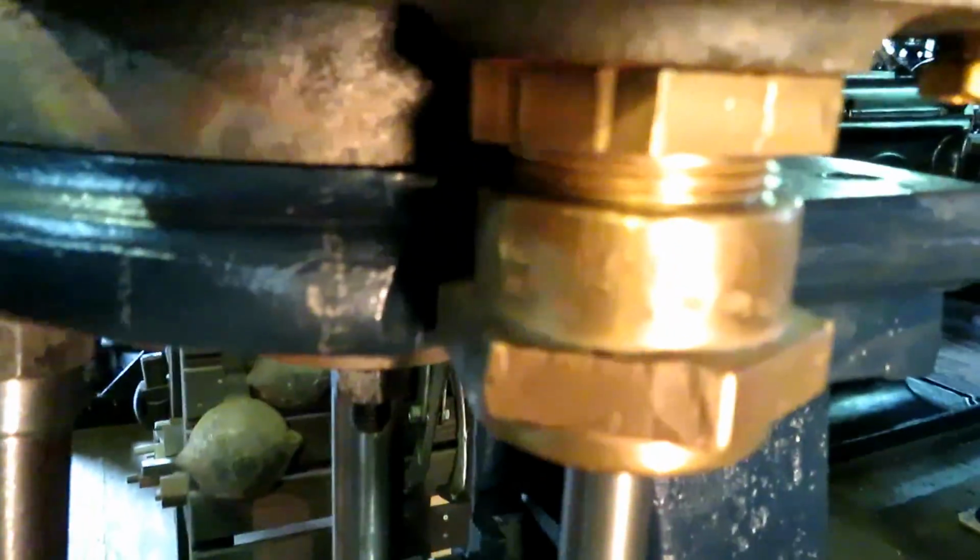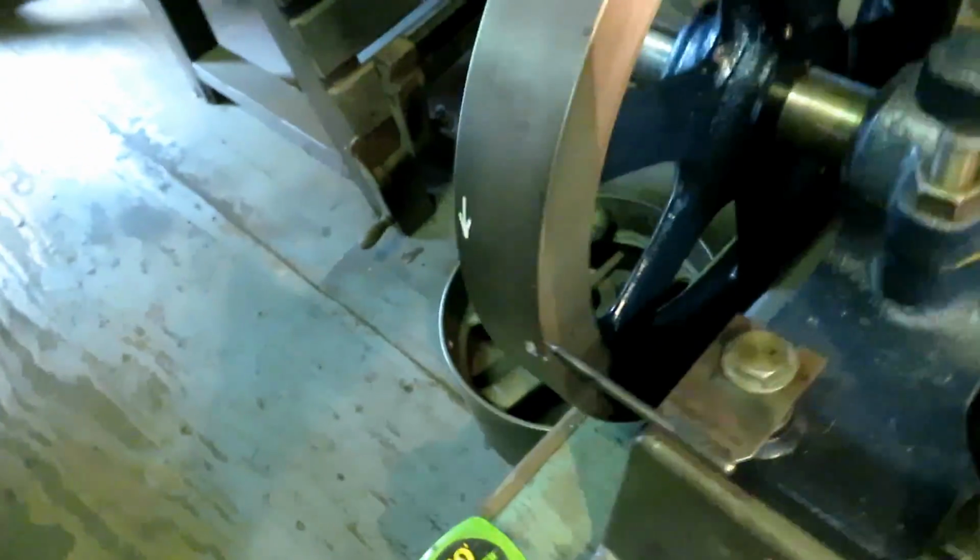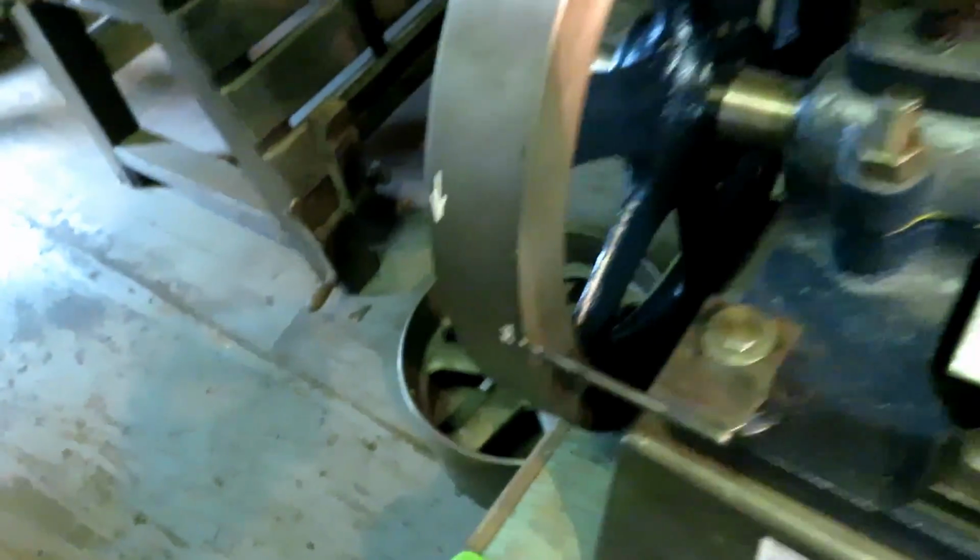And if I put this right on top dead center, that distance from the center of the valve, from this line scribed on the center of the valve up to that center line of the center of the ports, is the linear advance that's on the chart that I just showed you, and that's actually 0.644.